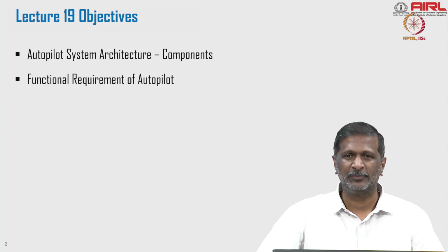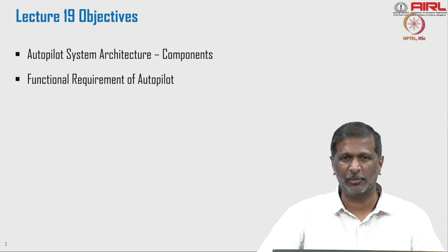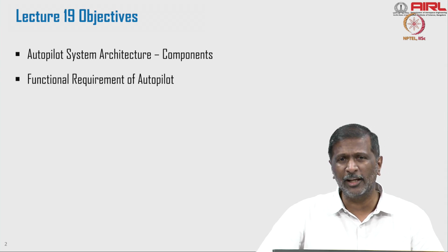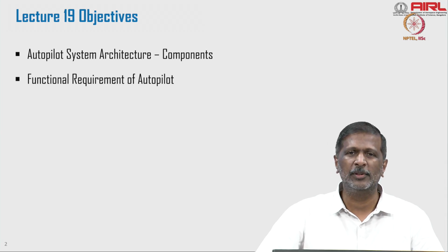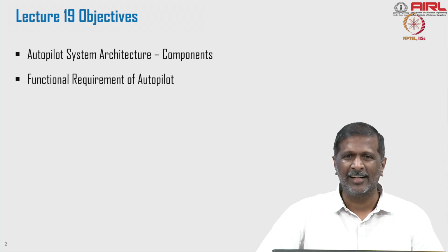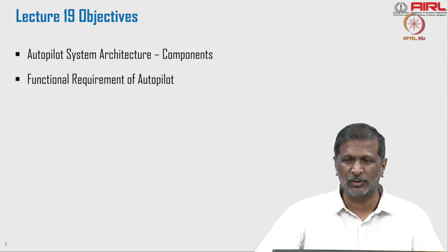All these are requirements. But those requirements cannot be taken in as they are. There is a need to convert the functional requirement to technical requirement. For example, if we say that it has to stop on the same level, we are talking about steady state error should be 0. Once my level is detected, first floor level, right? First floor is 1 meter away from the ground floor or 2 meters away from the ground floor. The lift should stop exactly at 2 meters. It should not have overshoot. It should not have undershoot, right? And you want the lift to go smoothly from one floor to another floor. It should not have an oscillation, right?